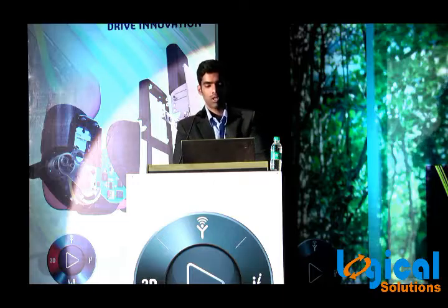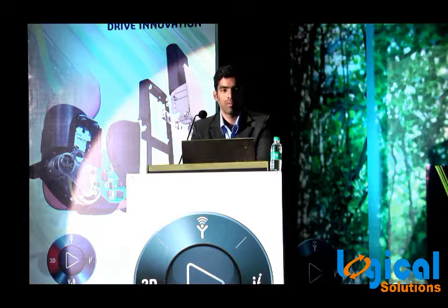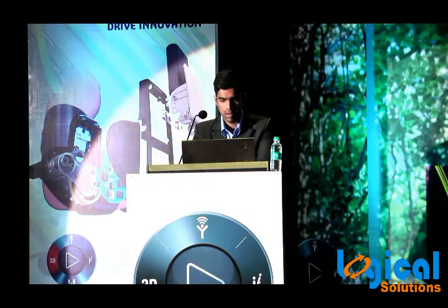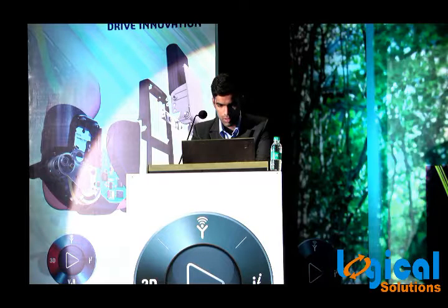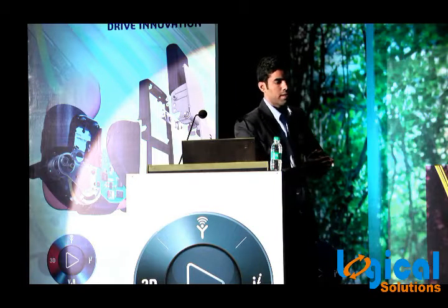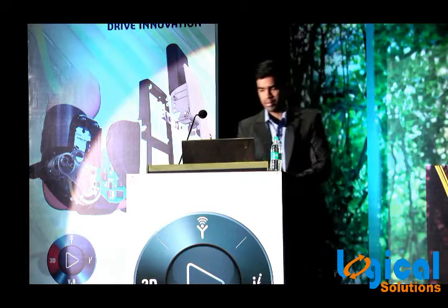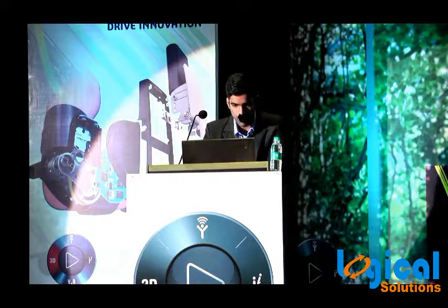You can select multiple sketches, as they will be added in the contour option. So you can use Instant3D and control the distance like this, such that a slot will be created on the plate with the material removed.